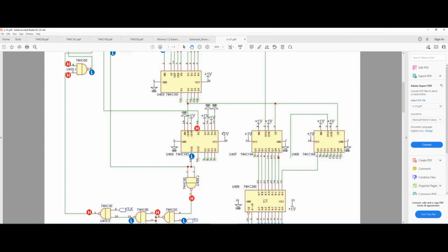What does it mean? It means you could set a value on the input side, and then once you set the value, when you pulse the chip, it starts counting down from that value until it reaches 0. However, during that countdown, as soon as you set the value on the input until it reaches the lowest value, it keeps one of the lines, called the TCD, or the count down line, high all the time.